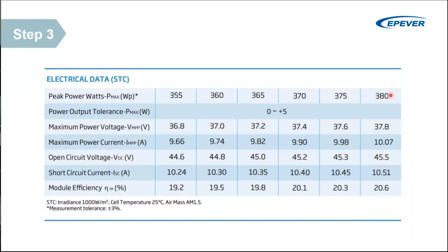You see a different voltage, VOC, open circuit voltage here, so it's not a nominal voltage. Nominal voltage is confusing for PV panels, and it is just used for classification. It's not a real voltage you are going to measure. It's not a fixed voltage either, and normally it's not mentioned in the PV specification sheet, so don't look for nominal voltage for solar panels in the data sheet of the panel that you want to purchase. It's a number that we associate to a solar panel to ease the designing process.